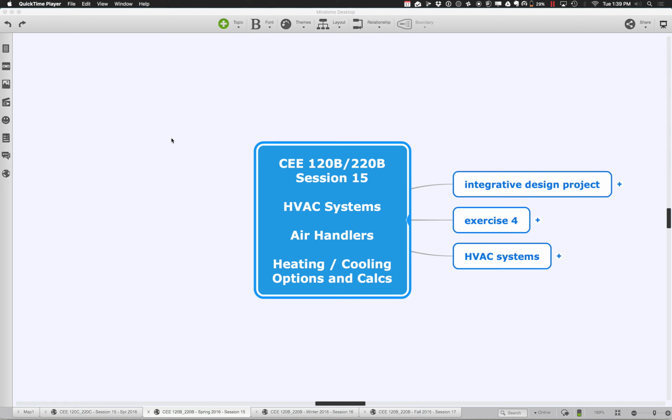It doesn't have to be strictly heat coming out as hot air from an air handler, coming out of some sort of a heating system there. We can do all sorts of things that are much closer to the destination, and oftentimes you do want to do something like that, because for every different zone and every different load on the zones in terms of the number of people, the occupancy hours, the heaviness of the use of those spaces, and even the type of use. Is it a steady, slow kind of use, or does it change and fluctuate very rapidly, in the case of a public room where hundreds of people show up all at once and then go away later? You often want to control things a little more finely.